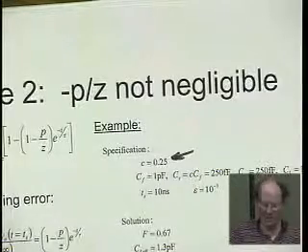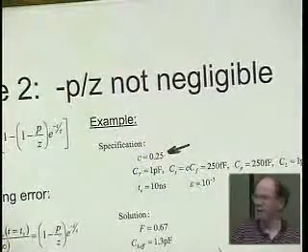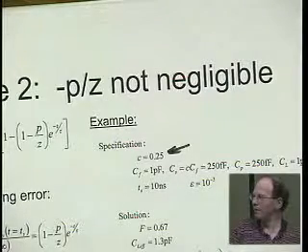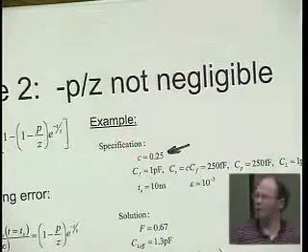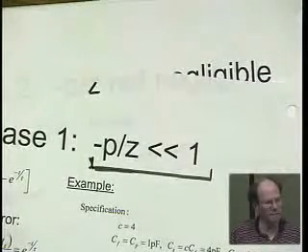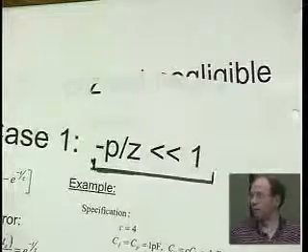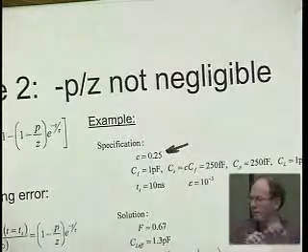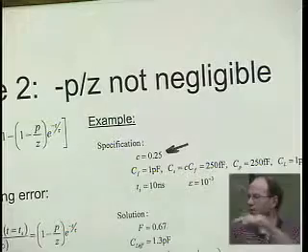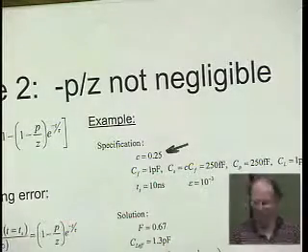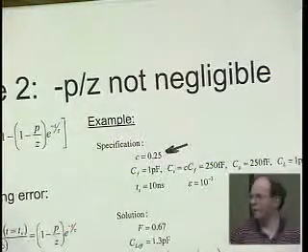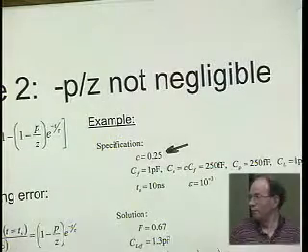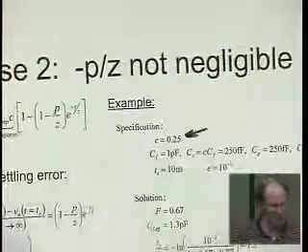In fact, once I had a student who designed a sigma delta ADC, and he started out designing a perfect amplifier based on this assumption. Then when he looked finally at the sigma delta, he said, gee, I need to actually attenuate my signal, otherwise I could go out of the supply rail. And then the amplifier design, a beautiful amplifier, was totally useless, because this equation said, yeah, you meet this spec, but you don't meet this spec. And this is what he wanted.